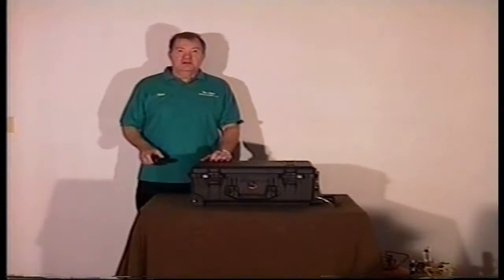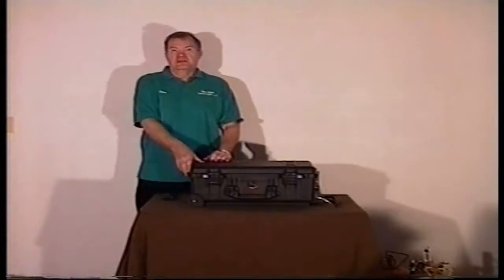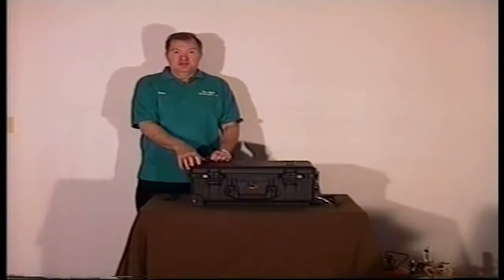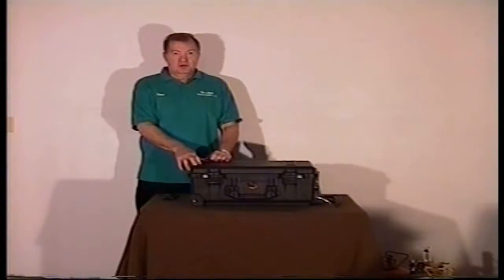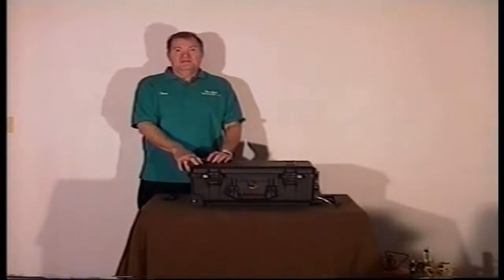I'd like to show you a 5-gas engine emissions analyzer we've developed for biodiesel and alternative fuels research. This analyzer will measure HC, CO, CO2, O2, and NOx. Plus it has 5 additional inputs for sensors of your choice, and it can be customized to the application. It's a PC-based instrument. All the data is saved in an Excel format.